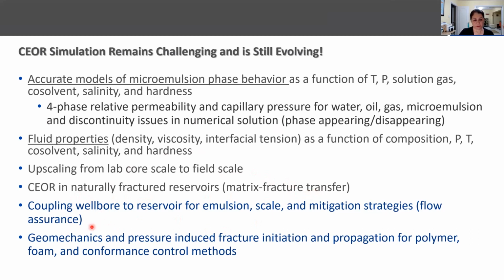Very important for flow assurance and for some of the mitigation strategies to couple the wellbore to reservoir, to be able to predict what emulsion you're going to produce in the producer wellbore, what kind of scale, and can we come up with some mitigation strategies. Breaking the emulsion and prediction of emulsion is a very expensive and scary topic for surfactant and polymer floods.